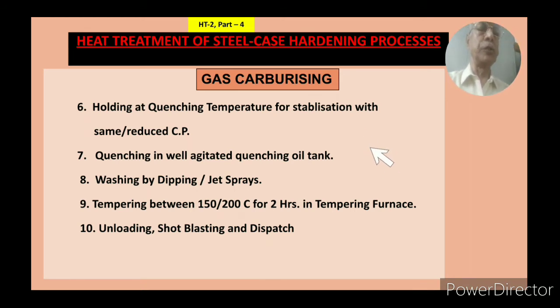You have to provide recuperators so that heat is transferred away from the quenching tank. The hot oil will go inside and the fresh oil will come outside, and it will maintain the level as well as the temperature of the oil. Okay, these two conditions are very required. And the third is your transfer time.